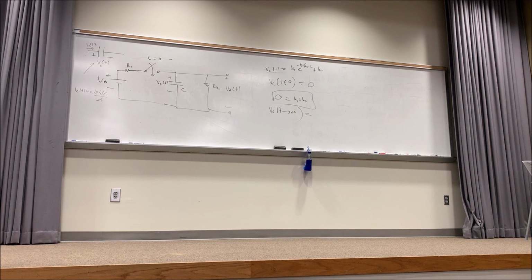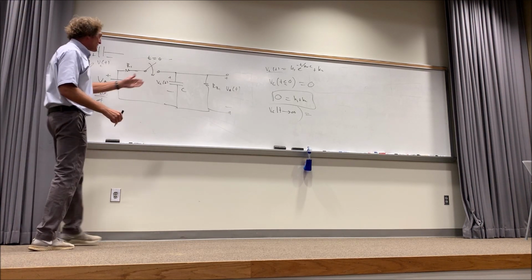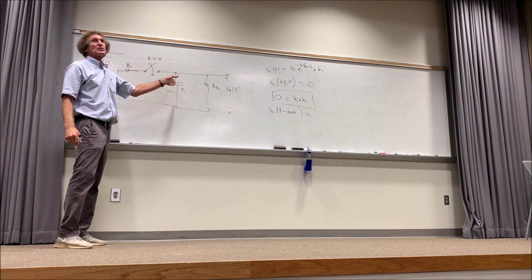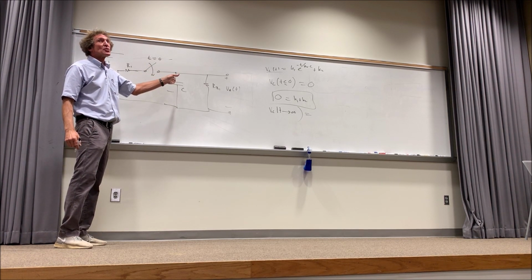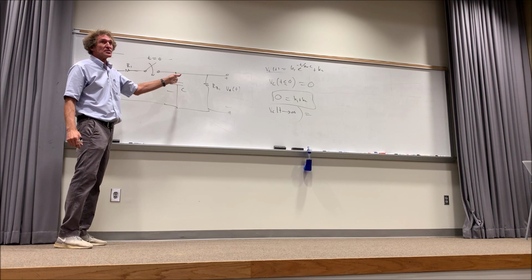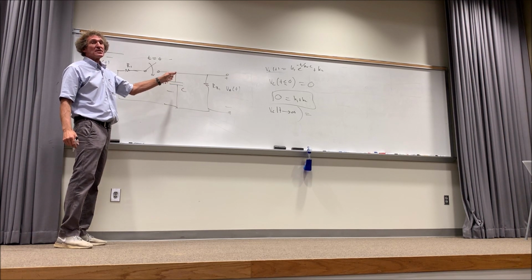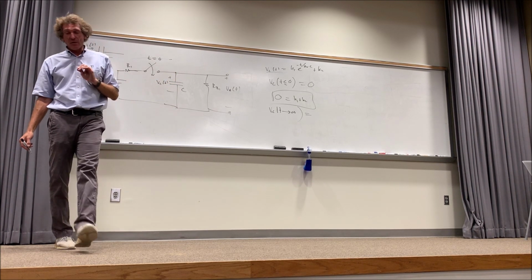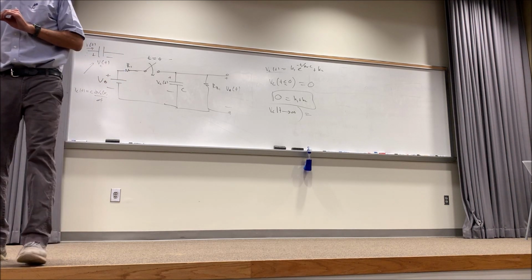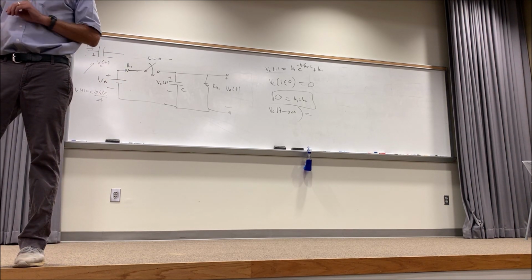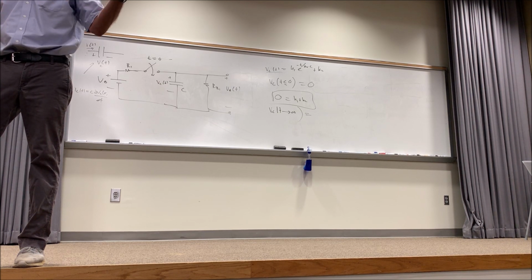It'll be a constant. Follow me? Now, another thing I'm going to tell you, that the capacitor looks like an open circuit to DC voltages. Did you hear me? A capacitor will charge to the value of the voltage. The charge Q will be equal to C times V. Whatever the voltage is times the capacitance will be the charge on the plates.